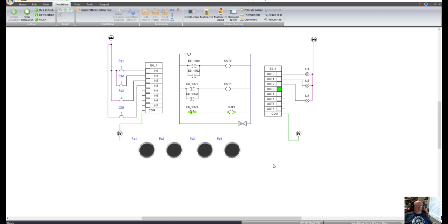And now, that's how you create a PLC program with Automation Studio. Now, again, you don't have to do this. You can draw it out on paper, but just make sure all your inputs and outputs are right. But if you want to use this, it does make kind of a handy setup. And once you get one set up with the inputs and outputs, then you don't have to delete the whole thing. You can just delete connections and reconfigure everything.